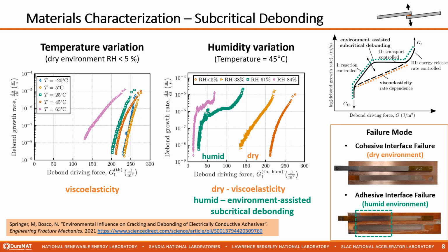Also, the failure mode is changing from a cohesive failure in dry environment to an adhesive failure in humid environments. These results confirm that cracking of epoxy-based ECAs is more likely to occur when high moisture contents are present.